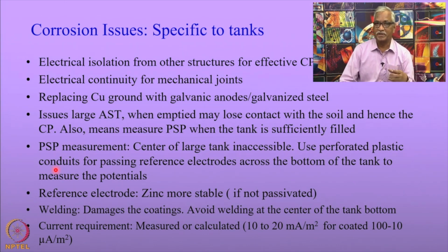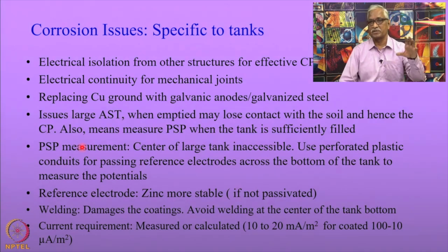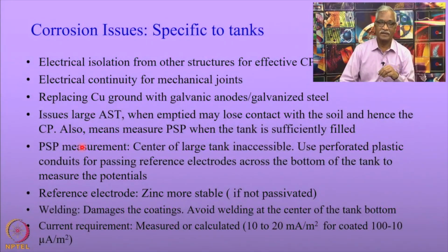So, measuring potentials of the structure towards the center of the bottom of the tank is always a difficult issue. In order to do this, people use perforated plastic conduits through which the reference electrodes are passed across the bottom of the tank to measure the potentials.